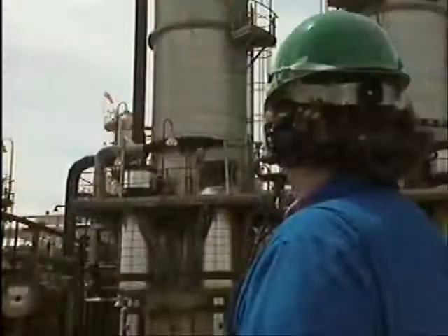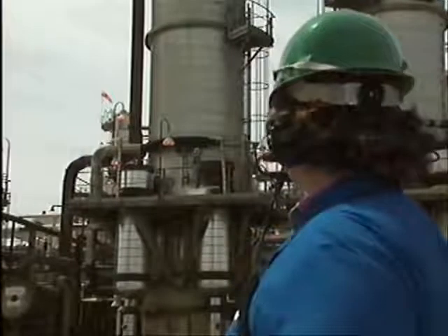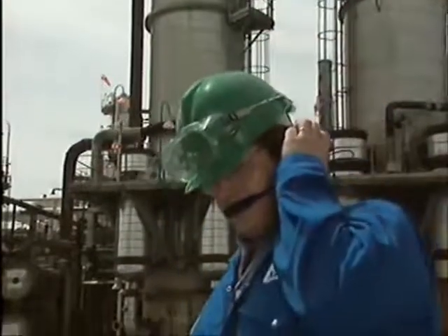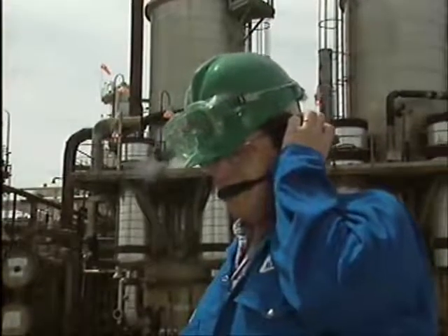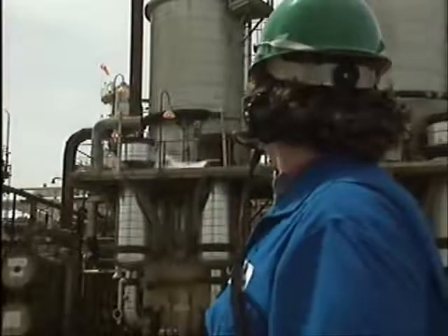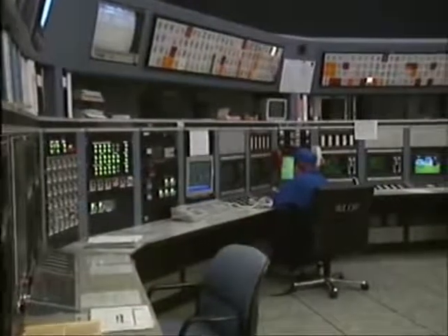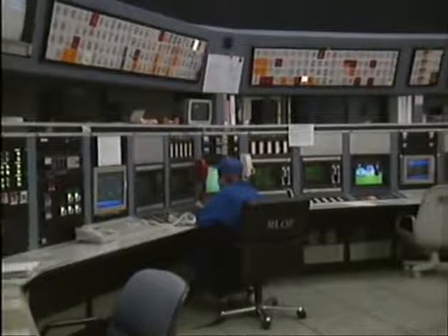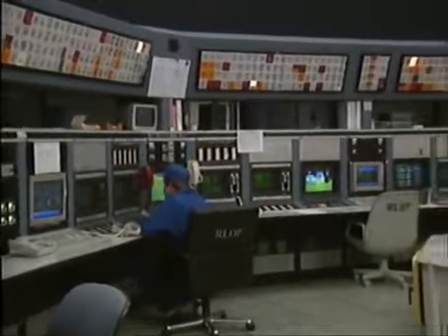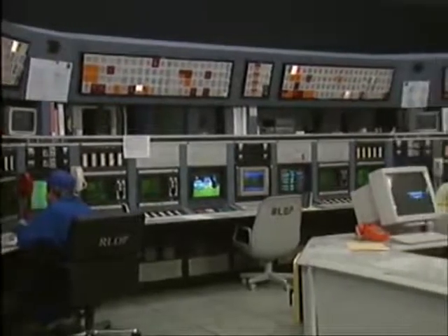properly. But anytime a safety valve is lifted, there's a corresponding drop in system pressure. So before you hand lift a valve, notify the appropriate operating personnel so that they can compensate for the drop in system pressure and keep it from interfering with normal operations. If operating personnel aren't forewarned, when pressure drops as you hand lift the valve, they might take emergency measures to raise pressure or to shut down the system. Such actions could be costly and perhaps dangerous.